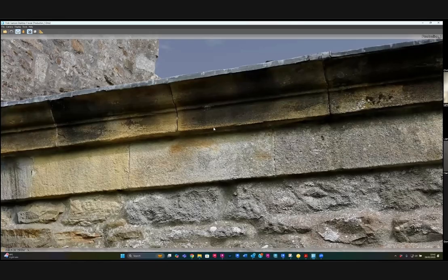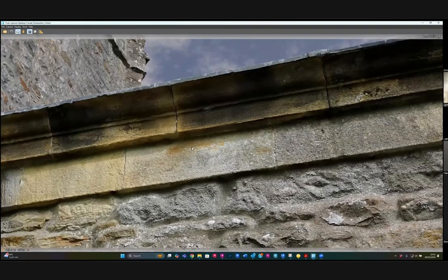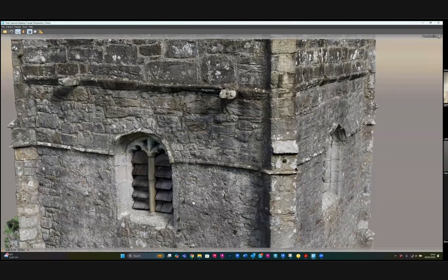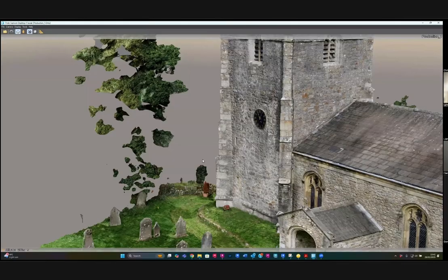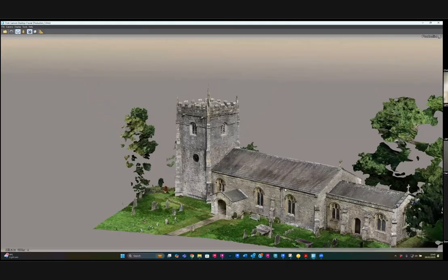As a rule of thumb, if you can't see crisp data and lots of information, then you've got to start questioning the accuracy of it. And what you'll find is, like here, we're flying up and down, looking in every angle, and it takes time to collect the data, whereas a lot of people, especially the companies selling drones, and I know I'm harping on about drones here, say, oh, fly from 15 meters away with your Mavic Mini, and you'll be able to deliver that, and you can class it as a measured building survey and draw your elevations off it.